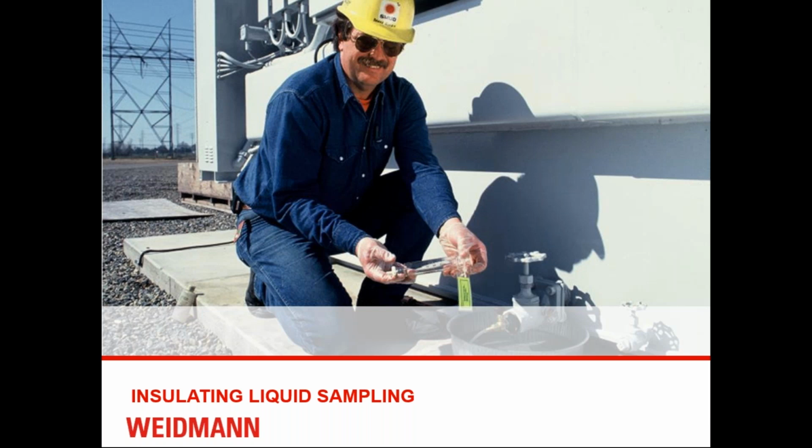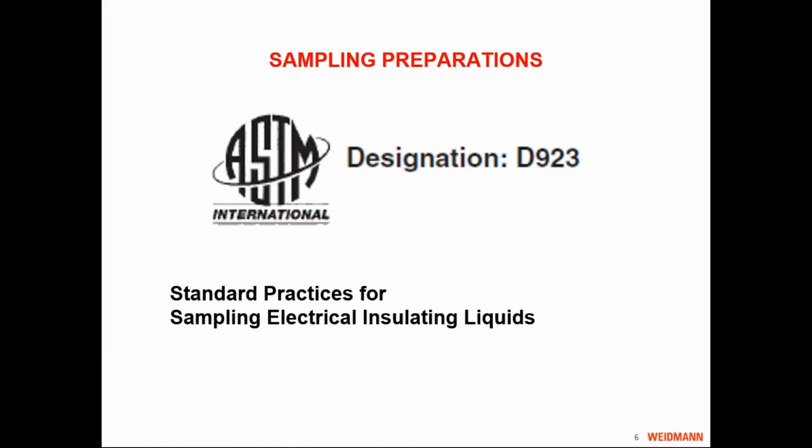Today, we're going to start off with just some high-level basics on how to take an oil sample to send to the lab for various oil quality and DGA testing. The only test we're really going to talk about today, which will come up later, is the dielectric breakdown voltage test. But this sampling procedure will work anytime you need to take a sample to send to a lab for some kind of testing and processing. Everything I'm talking about is based on this ASTM standard, D923, which defines proper procedures for taking samples from electrical equipment.